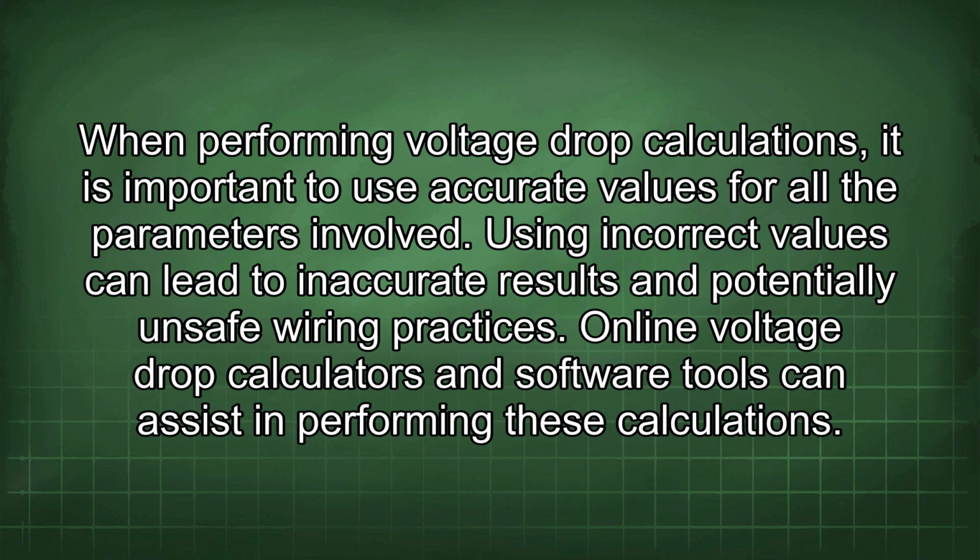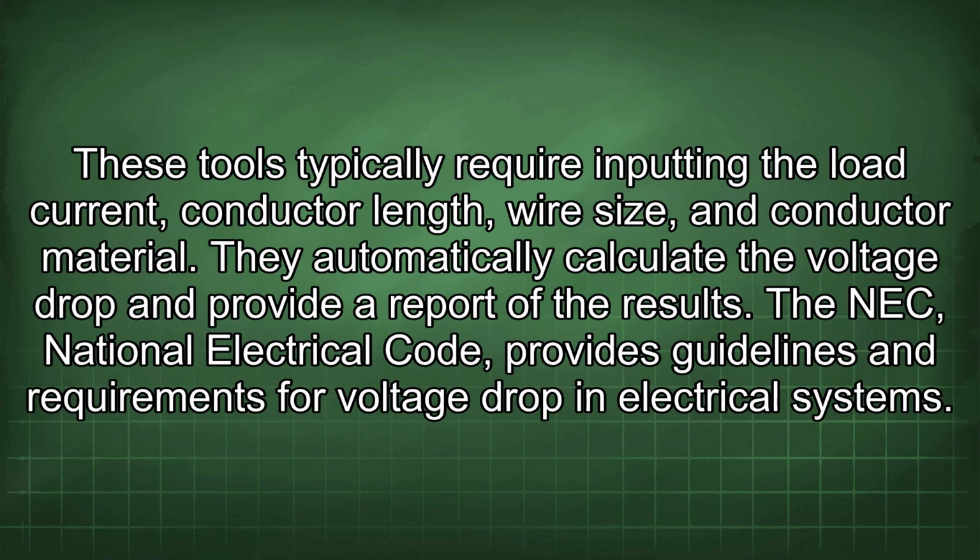Online voltage drop calculators and software tools can assist in performing these calculations. These tools typically require inputting the load current, conductor length, wire size, and conductor material. They automatically calculate the voltage drop and provide a report of the results.